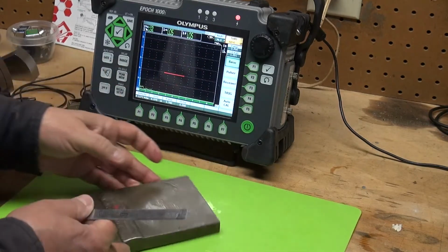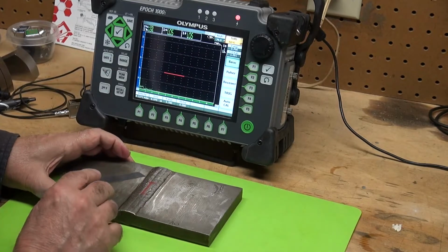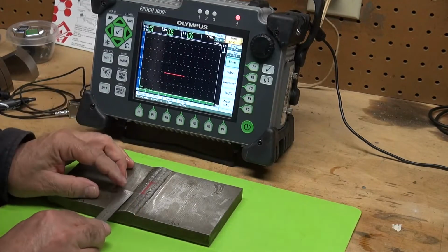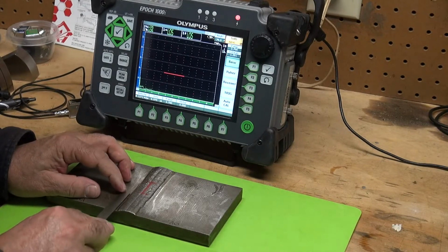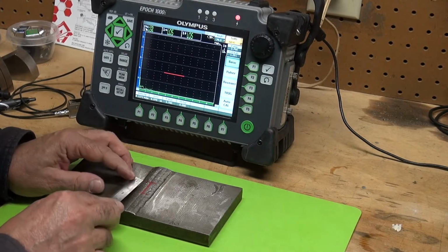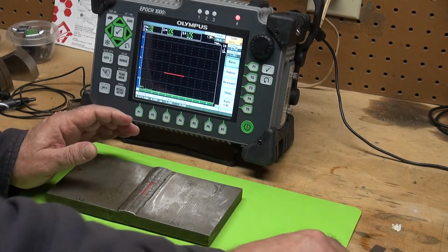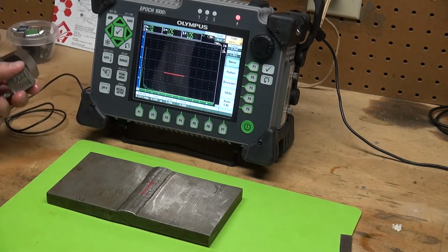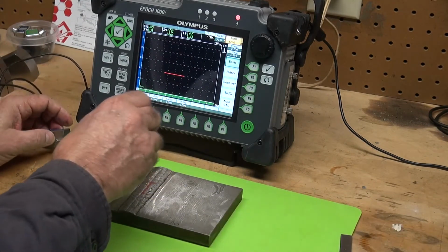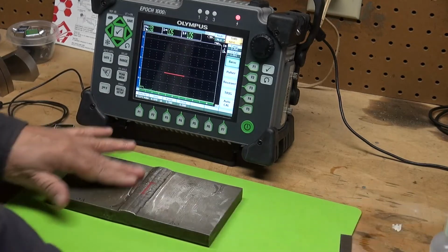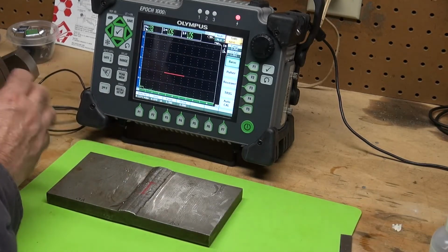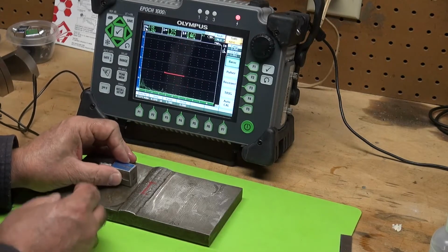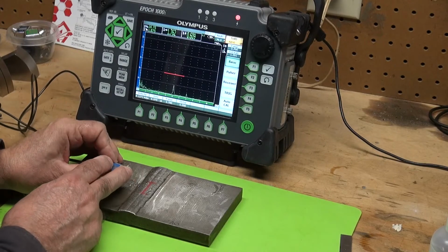Well, what I did was I transferred that defect right here. It starts at 1.5 inches from zero, and it's basically 1 inch long. So we can physically see it, and it gives us some confidence that we know what we're looking at. Let me put some coupling on here, and this is a 70-degree transducer. This 4 megahertz is good for finding ID connected defects like in the root.